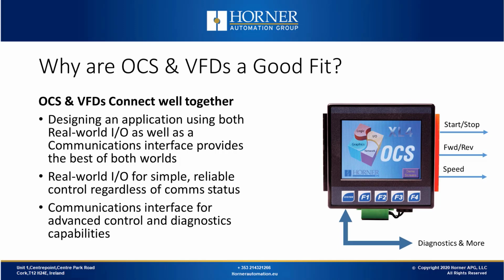For basic start, stop and speed control capability, you've got the ability to add either a full Ethernet or fieldbus based network connection or a basic RS485 Modbus RTU connection to not only start and stop the drive and adjust its speed, but also get complete diagnostics such as fault codes, etc. Live statistics like current readings and bus voltages are all available through those connections.